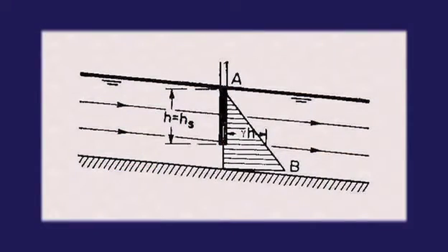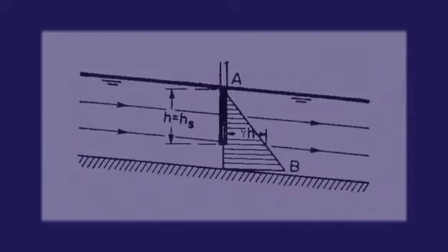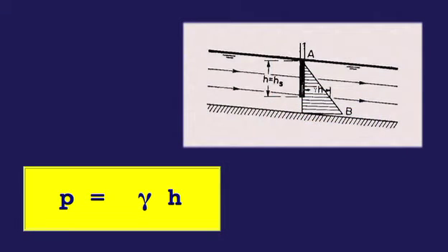The pressure is measured by the height of the water column at any point in the vertical. Under parallel flow, the streamlines have zero curvature and zero vertical accelerations. Conversely, under curvilinear flow, the streamlines have non-zero curvature and non-zero vertical accelerations. Under parallel flow, the pressure distribution is hydrostatic. That is, the pressure P at any point is proportional to the flow depth h at that point.